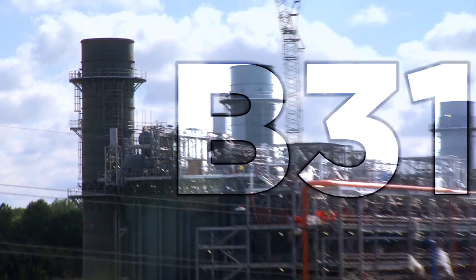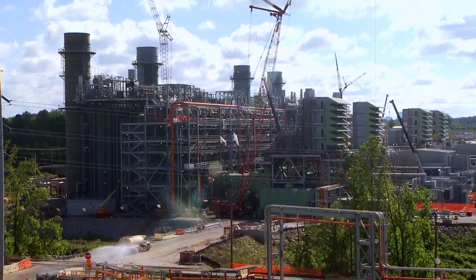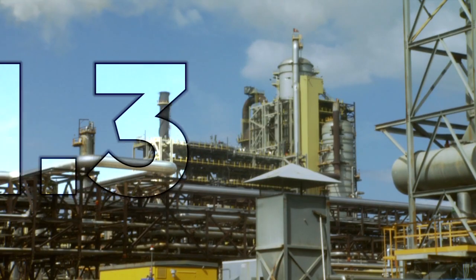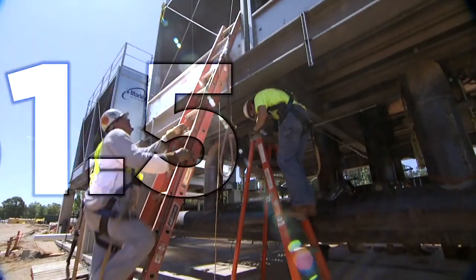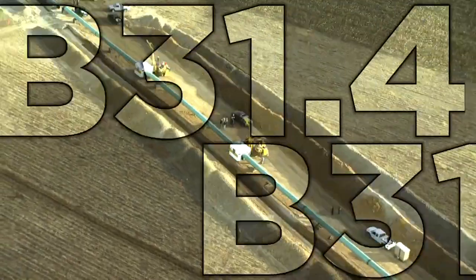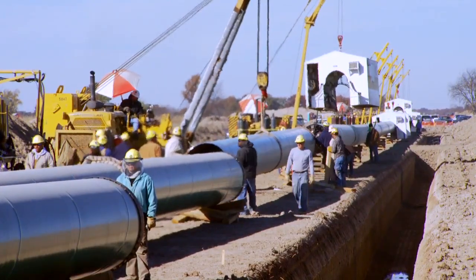B31.1 is for piping typically found in power generating plants and industrial facilities. B31.3 is for piping typically found in petroleum refineries, chemical and pharmaceutical facilities. B31.5 is for refrigeration piping, and B31.9 is for building services piping. B31.4 and B31.8 are for pipelines that transport liquid hydrocarbons and gases.